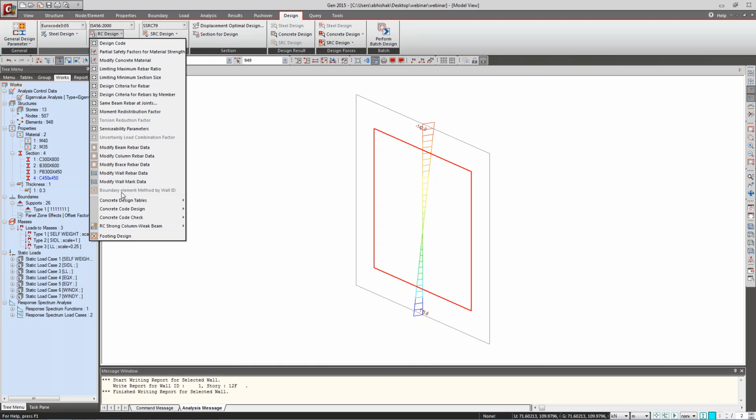Now Abhinav Hapse sir is asking one question: if the boundary element is required or needed to be provided in the shear wall, how can we model it in MIDAS? Generally, if the boundary is required, the design detail at the end of the section shows whether the end rebar is required or not. According to that, you have to provide it.